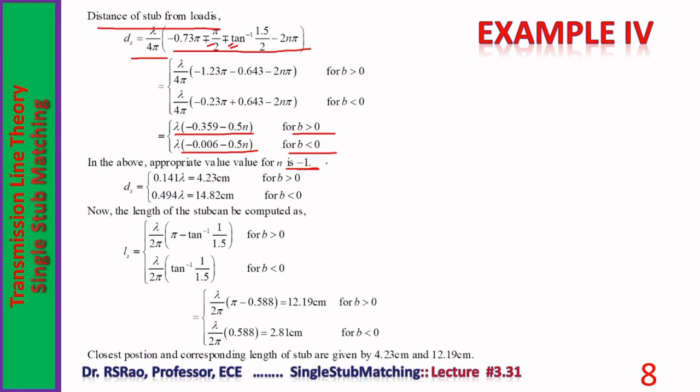So ds with n equal to minus 1 is 4.23 cm for B more than 0, and 14.82 cm for B less than 0. Out of these two, 4.23 is the smaller one. So the smallest distance at which the stub can be connected is 4.23 cm.